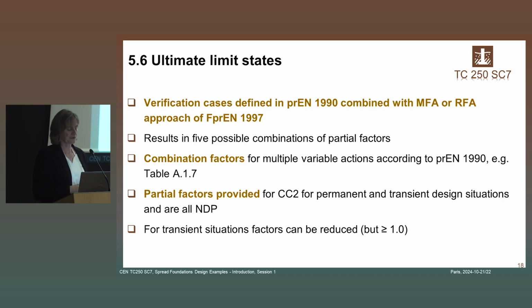Now, let's go back to the main text where the verification procedure for the ultimate limit states is dealt with in subclause 5.6. And because I focus now on part 3, I do not elaborate so much on what is written in EN 1990. As stated before, you have to work with 3 different codes, or maybe with 4. So we have EN 1990, you have all the 3 parts of EN 1997.